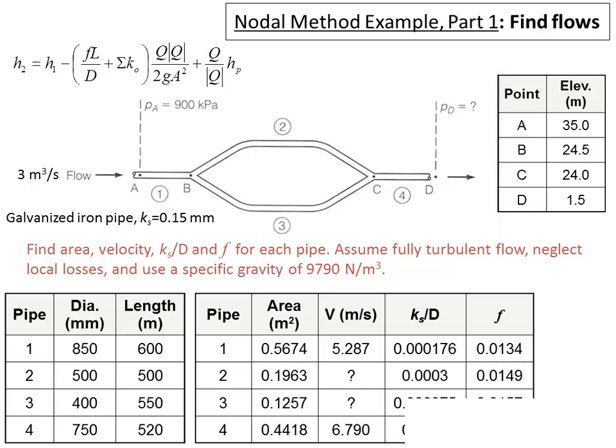We substitute in that expression in terms of V3, and that becomes the only unknown in the continuity equation. We can find the velocity through pipe 3. Once that's known, we can find the velocity through pipe 2, and then the flow rates through each of them, since the cross-sectional areas are known. And just to check to see if everything works out, we add the two flow rates together and find that it's 3.001 cubic meters per second. That minor difference is just on account of round-off error.